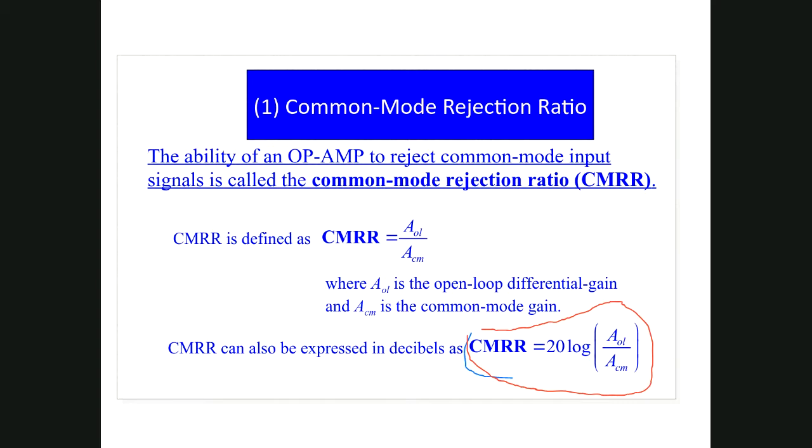For example, if you're designing a circuit for audio communication, you may be a bit flexible. Why? Because our ear is not very sensitive. Some imperfection it will accept, but when you are designing something for video signals, our eyes are very sensitive compared with the ear, right? So in that case, even a small value of common mode gain will not be acceptable. You got my point, Muhammad Salman?